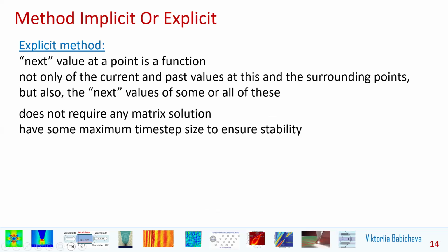The finite difference methods in numerical time integration of equations can be done explicitly or implicitly. The main advantage of the explicit scheme is the possibility of solving each time step without the need to solve a system of equations where all the degrees of freedom are involved. Its disadvantage is the stability of the solution, which in many cases leads to time steps that are too small to be efficient.